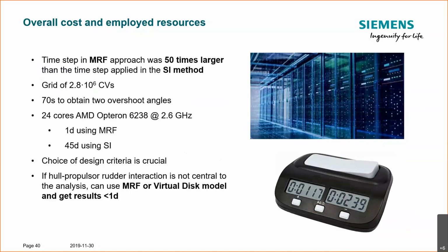And that is only due to the fact that for the sliding interfaces, the time step was chosen according to resolving 2 degrees of propeller rotation in 1 time step. So that's a very, very small time step. All in all, even though we get very good results and can study everything we want, what hydrodynamicists can dream of, having the CFD simulation of the maneuvering, the choice of the design criteria is very crucial. So let's say I just want to look at the hull and how the hull performs, and I want to do direct maneuvering simulation.